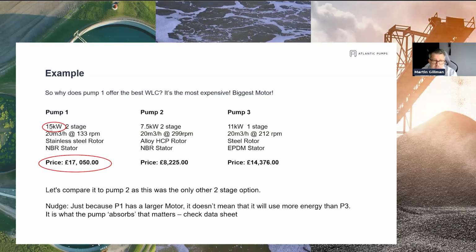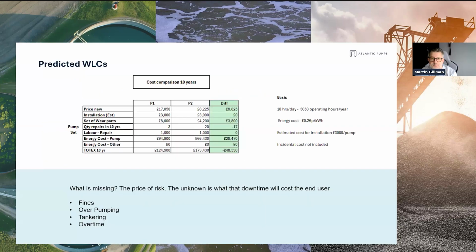But just because this has a 15 kilowatt motor and this has an 11 kilowatt motor, it doesn't mean that that's drawing 15 kilowatts and that's drawing 11. That's not how it works. You've just got enough power to start and run the pump. That might only be working with 9 kilowatts for all we know, and this one could be 10. So it doesn't necessarily mean that. I'll show you an example of that perhaps in a moment.